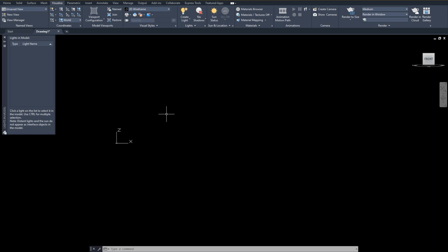So how do we start with this? We start from the 0, 0 point, obviously, and I suggest you draw a line about six inches long. For that, the UCS has to be set to the X and Y coordinates. AutoCAD has something very important to remember: it only generates lines on the XY coordinates when you're working to create a design. So if you want to draw a straight line, type UCS, enter, and make sure your view lines up with the XY coordinate plane.